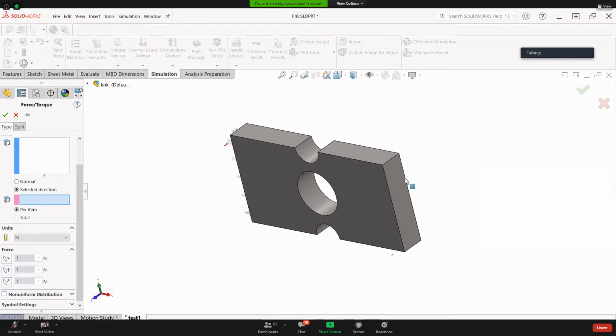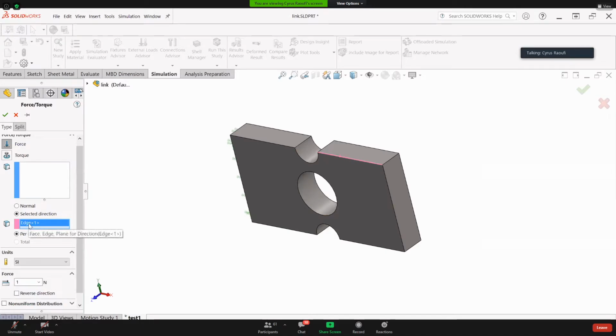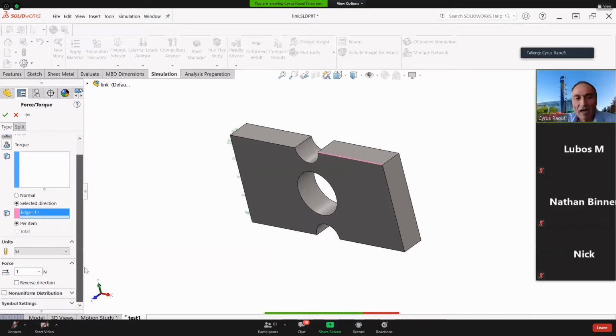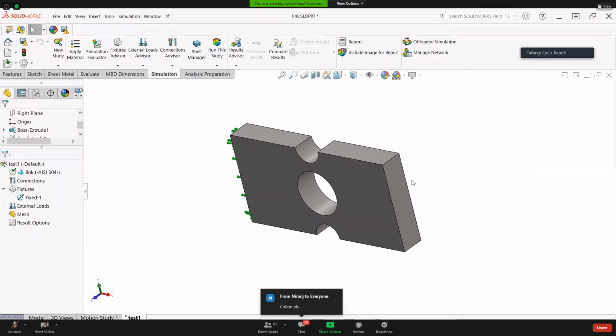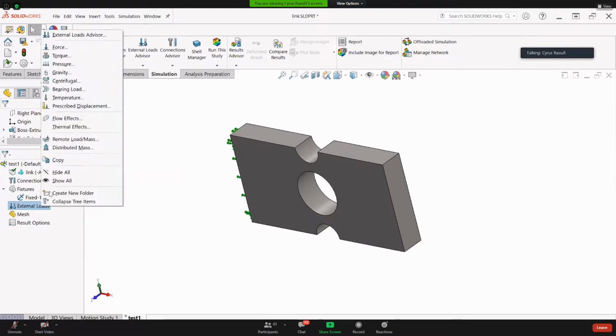All right. Now, what's happening here is, if you go to those pages that I mentioned, you can apply force in any direction. You can select this edge, for example, and then that edge is selected, and you can say apply force to this edge and define the other parameters. Again, we are going to talk about those, but as a reference, please read pages 24, 25, 26. Now, I'm going to apply a force.